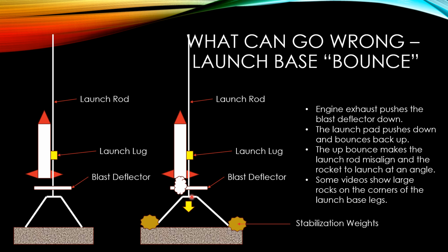So again, some of these under slow motion analysis will probably exhibit this bouncing effect where the pad will drop down and then snap up, and then the rocket itself is going to find itself jiggling on the rod because of that quick snap. It's like a tight rope, and snapping the end of it, it's going to make these bounces go back and forth, and it's going to whip the rod. Again, it happens very, very quickly, but it happens enough that it does add some level of unpredictability to the actual launch. So again, the solution that I have seen are these weights here and here.